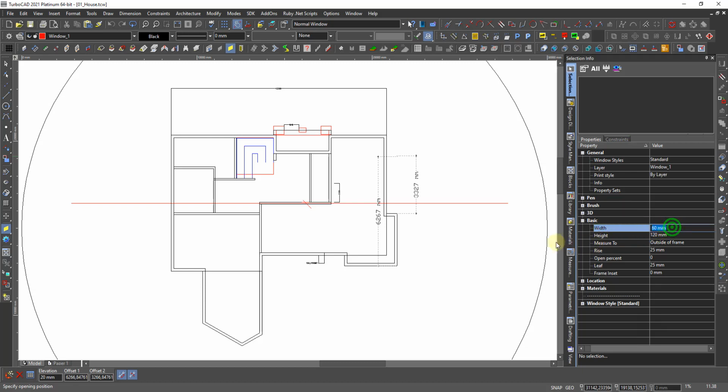The window, I use the basic window that is 1.2. 1.1 by 1.2, width by height. So that is, and we are also using 10 millimeter less than the full measurement in this modular system we're using. So then it will be 1090 and it should be 1190.